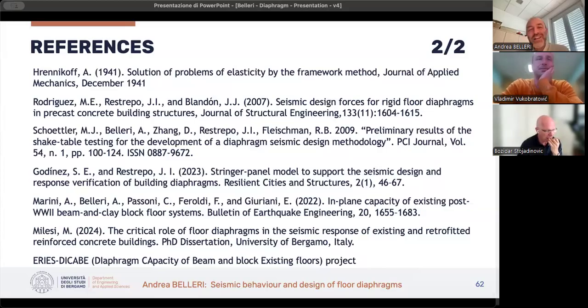So that one, we didn't cover timber diaphragms. In existing historic buildings, there are some solutions to provide stiffening of existing timber diaphragms by providing an additional layer of timber sheet elements. That's one solution.